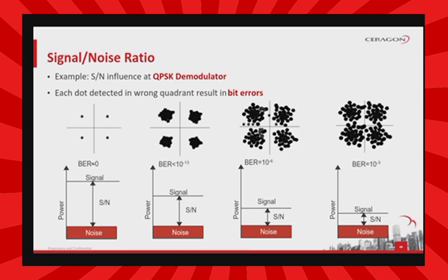The relationship is clear. The lower the signal-to-noise ratio, the higher the number of errors received. We are showing this to exemplify the correlation between signal-to-noise ratio and the bit error ratio, which determines the link quality. The SNR values are not presented in Ceragon machines, but what you will see and utilize is the mean squared error values, in decibels, which follow the same correlation shown here.